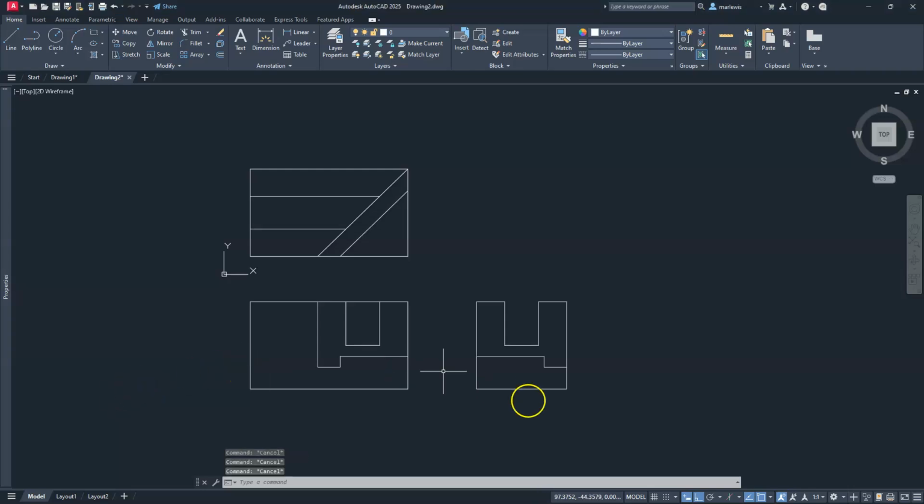All right, so remember that to set up the isometric, it's just simply selecting here. That's going to put me in an ISO draft. You should see that your cursor, or icon, should move. And remember that we control that with the F5 key, or you can come next to it and select which ISO left, top, or right that you want to be in. And we're going to start off on ISO left in this case.